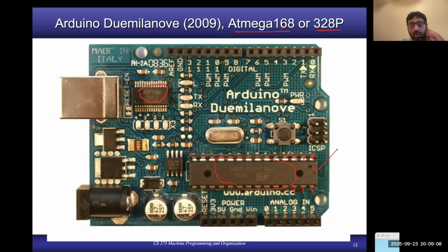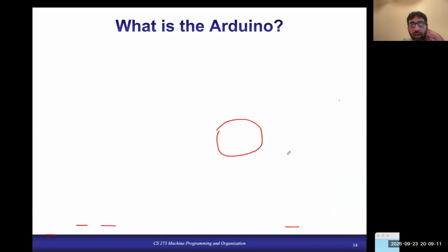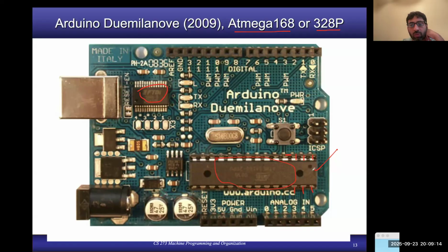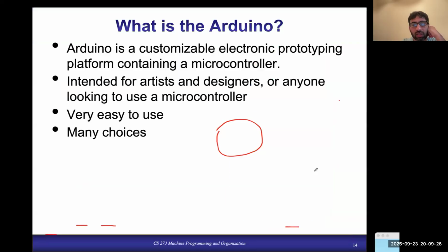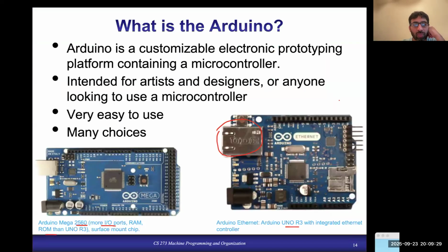So that's why your Arduino Uno R3 is good for prototyping. Even if you are not using an Arduino board but you have this chip, you can simply put it in your breadboard, because it has legs which can go inside the holes in the breadboard. As compared to this dual inline packaging, here you have this flat package. In the case of this package, the pins don't go inside holes on your printed circuit board. They are soldered on the surface, so they don't pierce through the board. That's why they are called surface mounted chips.